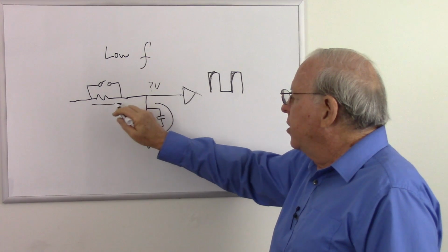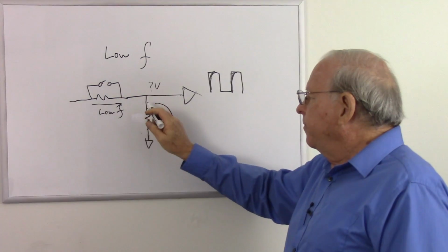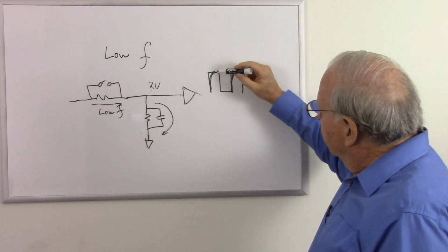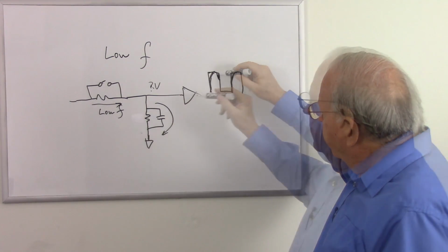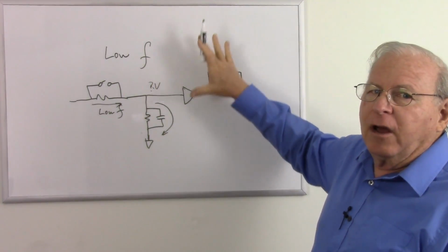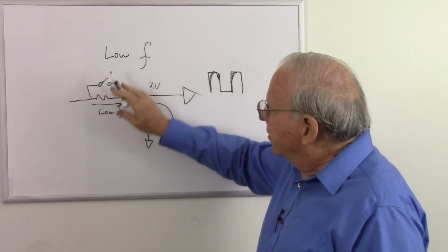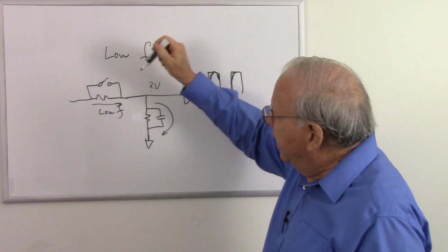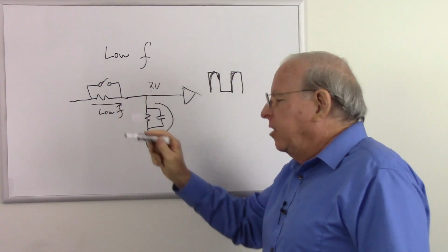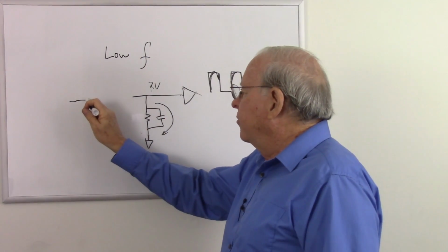So there it is. And so we want to block those low frequencies, but yet they're able to go through this resistor here. So our low frequencies, some of them go through that resistor and are able to develop a voltage here. So we're not completely blocking the low frequencies. Those low frequencies will tend to round off this edge here. And with the low frequencies making it through, it might not even oscillate. And if it does, it's going to be more dependent on the other resistors and capacitors instead of this filter circuit. So we don't want the capacitor in parallel here, because when it becomes an open circuit at low frequencies, the low frequencies can still get through that resistor. So we really need to have them in series in this part of the circuit.